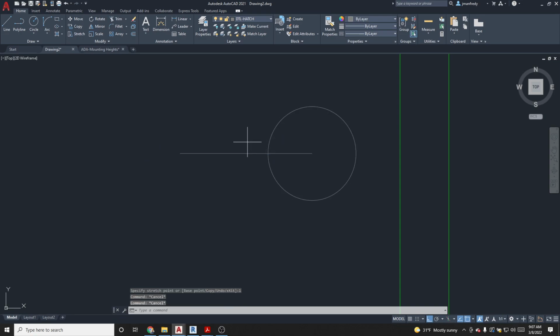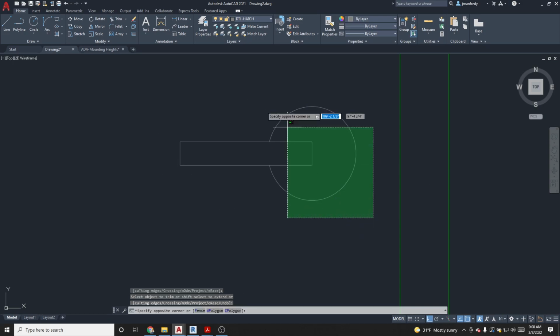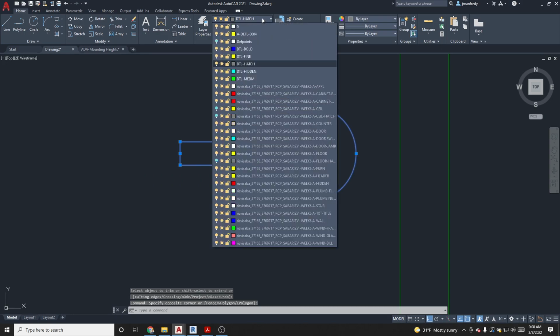And I'm going to offset O, let's say a ½ inch. Let's not do a ½ inch, that's too much. Offset 1/4 inch, up and down. Draw a line across the end, draw another line across the end. This is 3 inches over, this is ½ inch up and down from the center. I don't need that anymore. Trim, I don't need that anymore. There's the handle. I'm going to take the entire object and move it onto the Detail Fine layer.